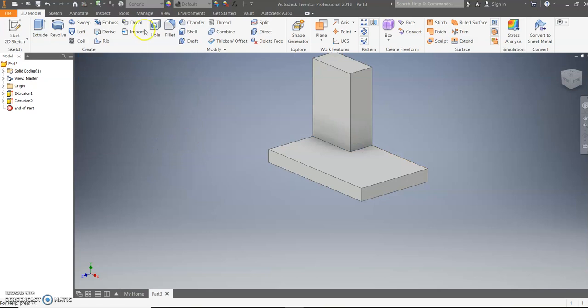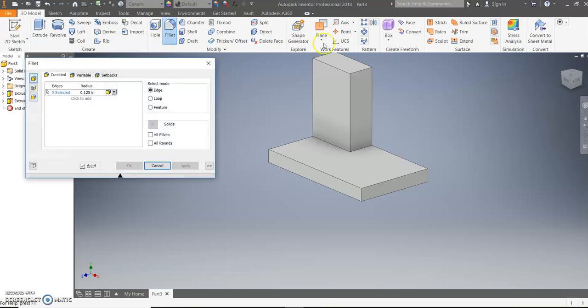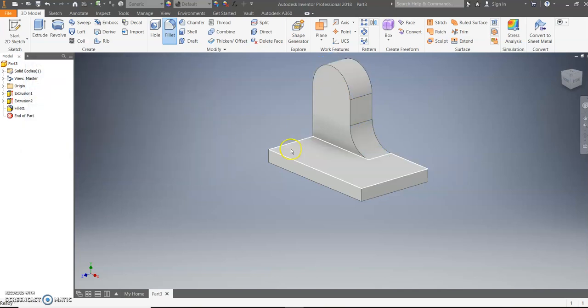Now we're going to start by rounding off some of the edges. I'll do that by using the fillet tool. We'll click on the top edge, and it's going to have a radius of 2. Same thing on this near edge. And then as we come down on this inside edge, it also gets a fillet of 2. So that gives us those edges as 2. I'm going to hit OK, and that gives us our overall structure there.